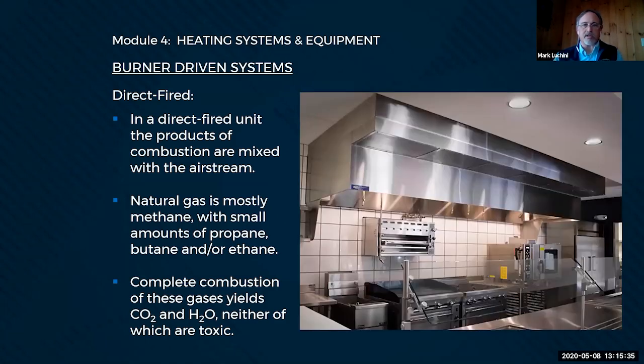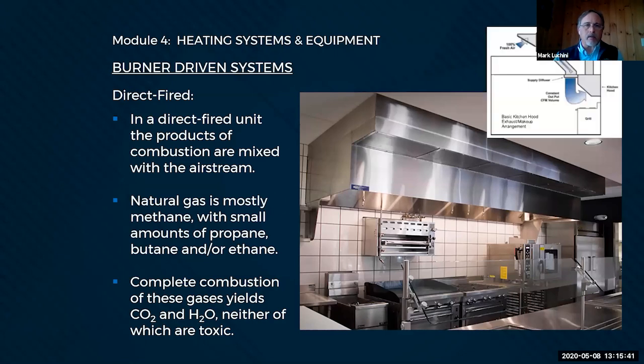Most common place you're going to see that is on kitchen ventilation. So graphically, what that would look like, you have your fresh air coming in these diffusers right in front of the hood, and it gets just sucked right back out to the exterior. So short circuits, does not really get a chance to build up any kind of potential contaminants.